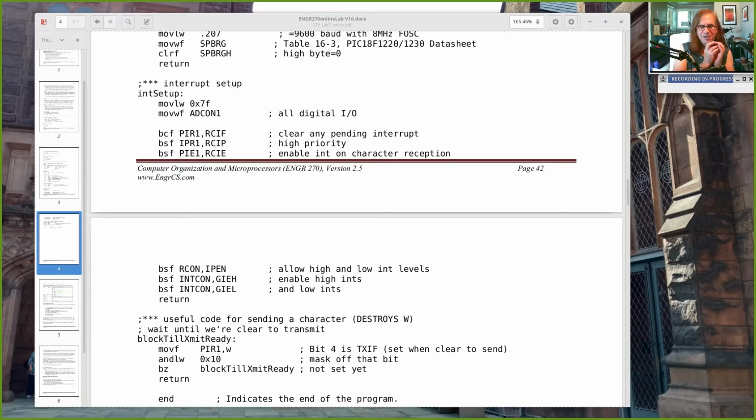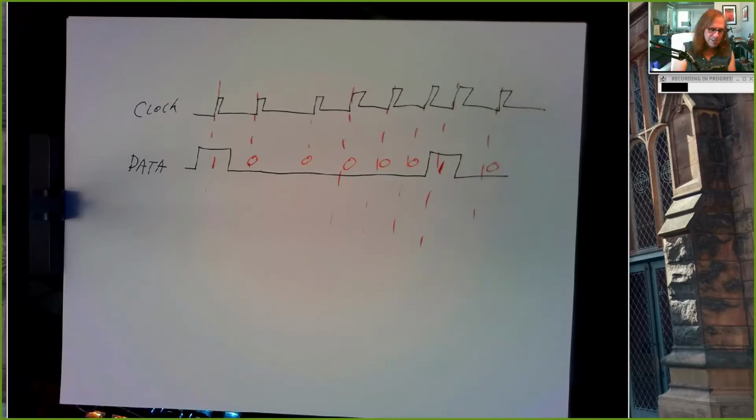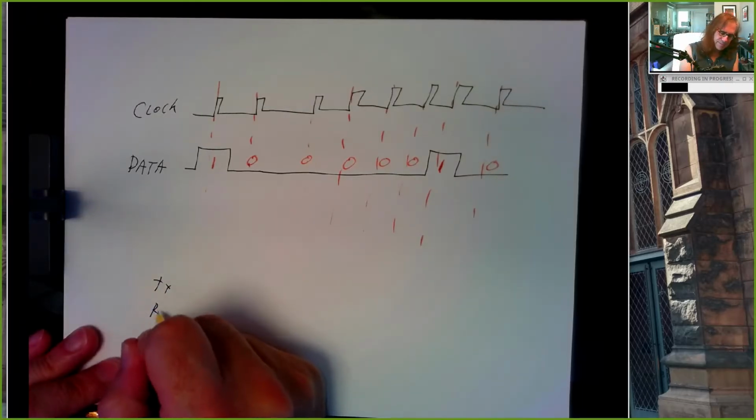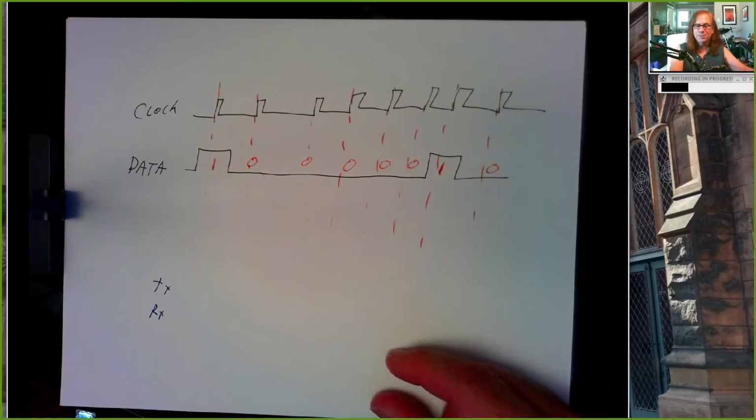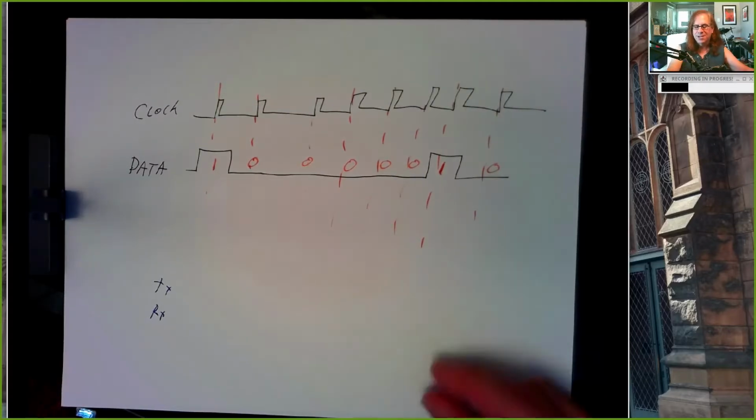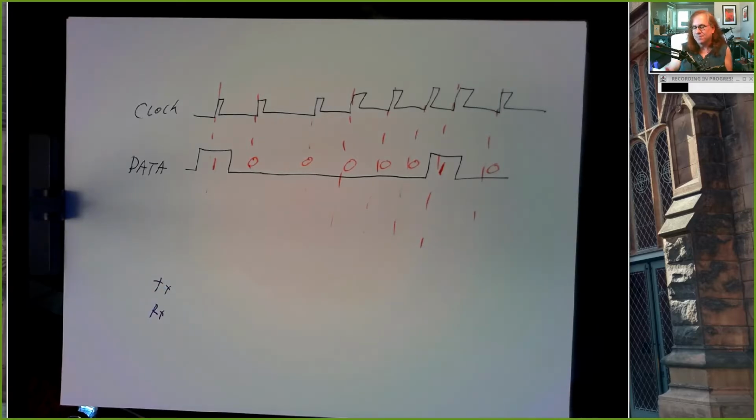But if you have an Arduino processor or a Raspberry Pi or an ESP32, they all have a pair of pins labeled TX and RX, and those are serial communication lines, and that's basically RS-232. So if you had a serial device, you could hook it up directly to pin 0 and 1 on an Arduino and communicate in serial. Now, most Arduinos come with a USB port, but guess what? They have something like a CH340 to translate from the USB to these serial lines, and then you can talk through the serial port.